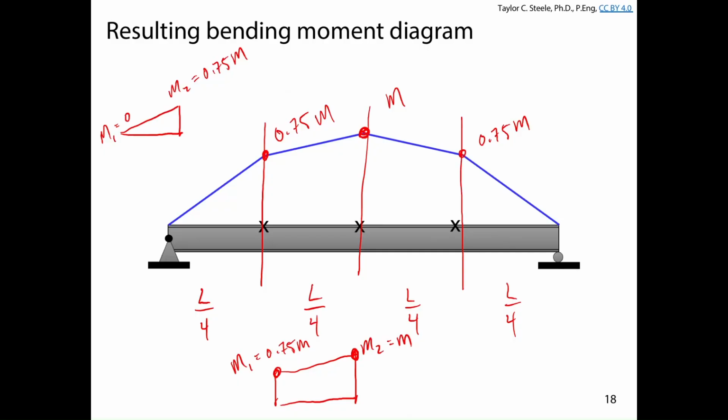And because the moment diagram is closer to being constant, right? We've got a kappa value here of minus 0.75, and that's going to make omega 2 closer to 1. It's not going to be equal to 1 because the moment diagram is slightly different, but it's going to be equal to a little bit more than 1.